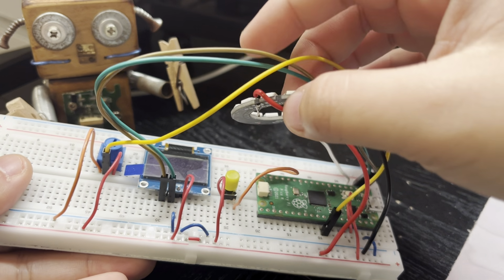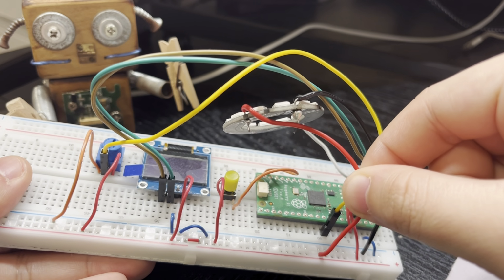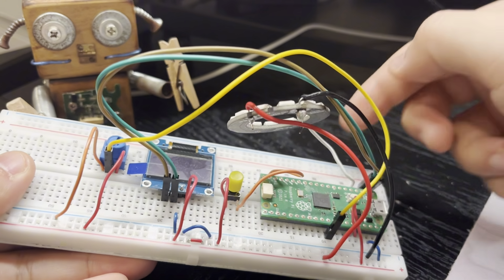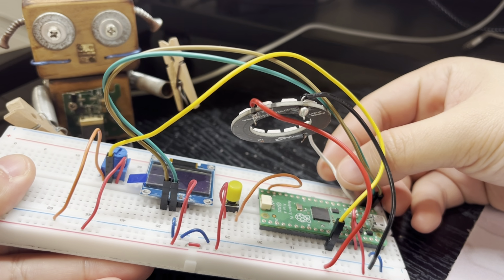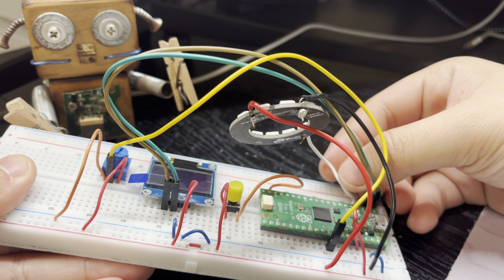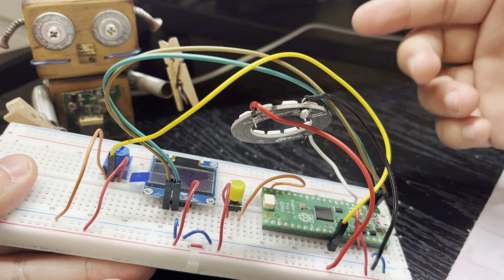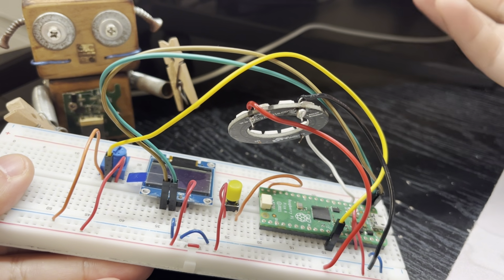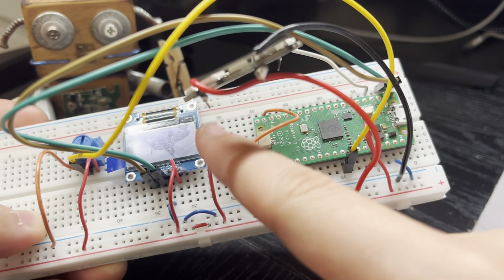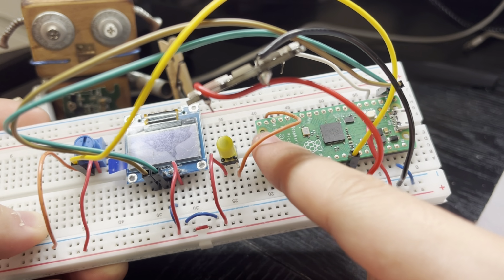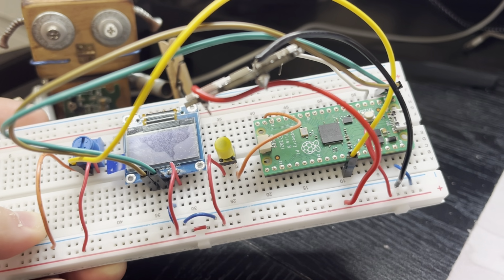For the NeoPixel LED ring, power goes to the breadboard voltage line, ground goes to the breadboard ground line, and the white wire here, which is the data input, D1, goes to GP2 at pin number 4. This allows the Pico to control the LED animations, like rainbow, color, green flash for a hit, and red flashes for a miss. For the button, one leg goes to the power right here, and the other leg goes to GP14 at pin number 19. The button is used to start the game and to shoot at the target.